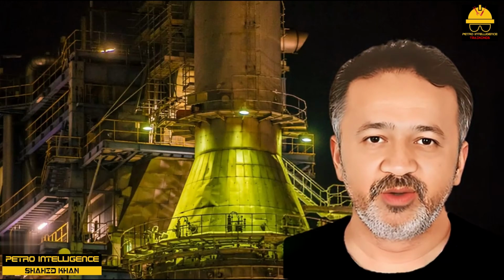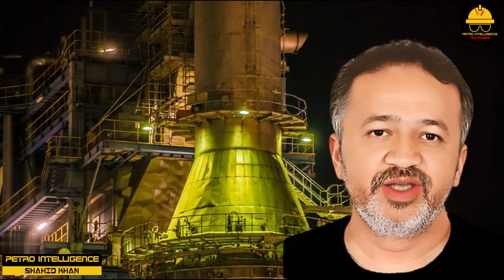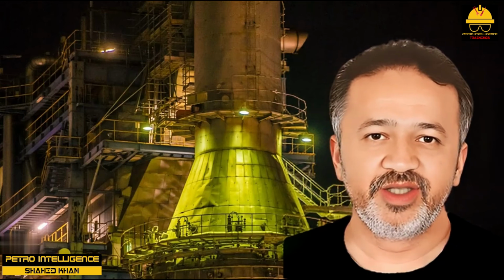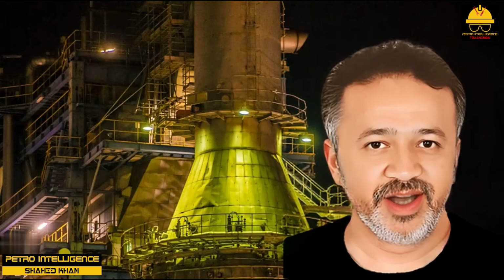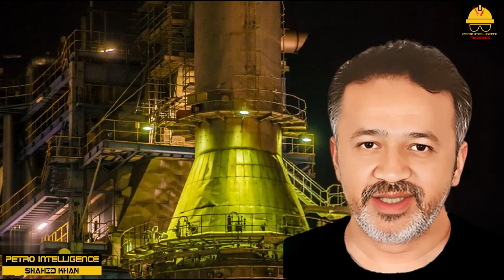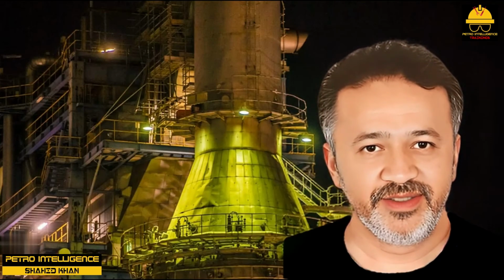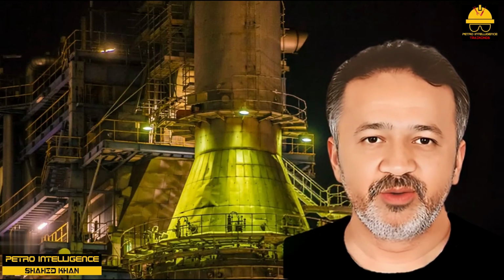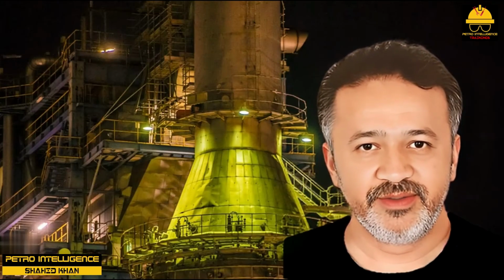Minimizing fuel wastage due to air leaks. Suppose we now cut back on the combustion air by closing the air registers a little. The oxygen content in the firebox is now 3%. The oxygen in the convective section will also be reduced to, say, 9% oxygen. Notice how the difference between the firebox oxygen and convective section oxygen, which we refer to as delta O2, has increased. It is now 6% O2.